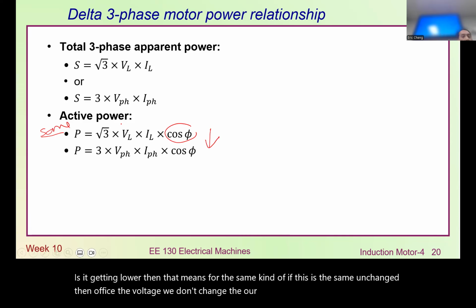But if in your motor the windage loss is negligible, small, then you can assume this resistance is equivalent to the core loss resistance. I think you do remember that when we worked on the T model, right? We do have a resistance here, they call it RC, right? So that could be this resistance. However, this resistance could also be a component for windage, friction, and also core loss. So this resistance will be a combination of a number of things. We don't know yet, so that's how we can estimate. All right, any questions up to this point?